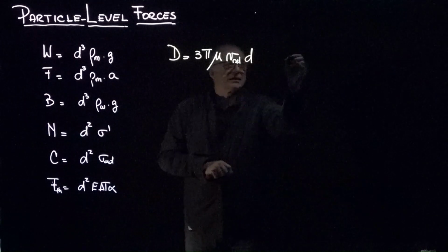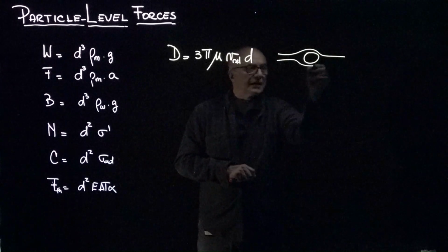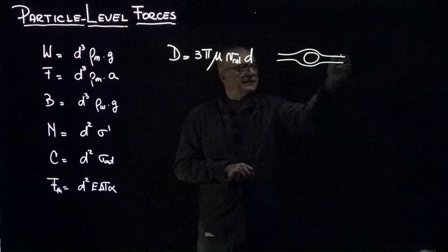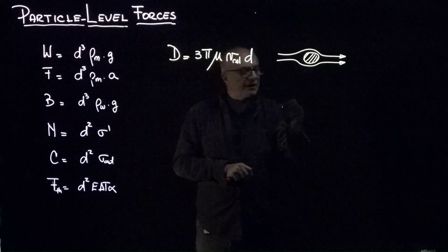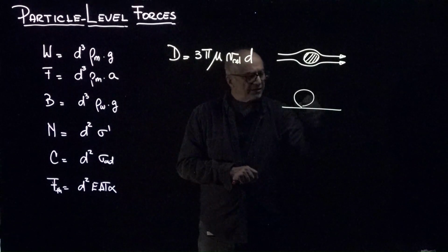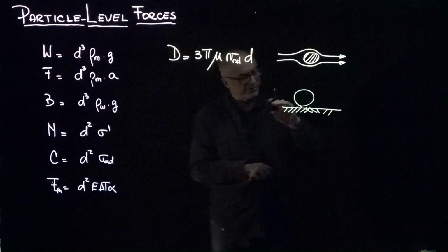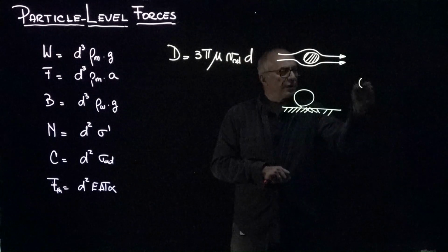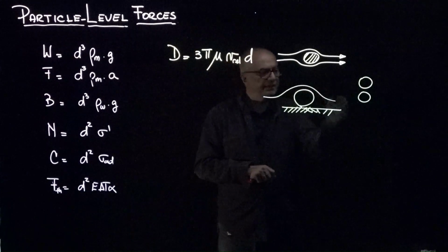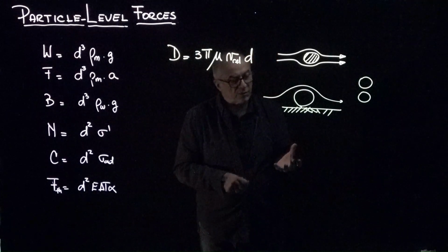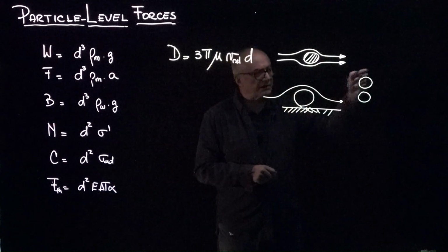This is when the particle is moving relative, once again, to the water and creates streams like that. But there is one more situation that develops here, whether the particle is resting on the surface of another grain or a rock mass in the case of a fracture, or there are two particles in the medium. Now the flow lines are different, and they create like a wing effect that lifts the particles, and that causes the saltation of particle migration.